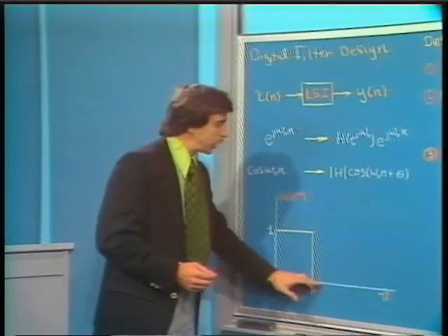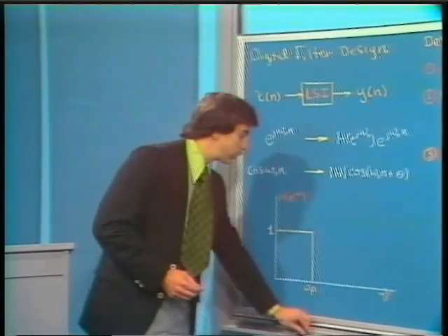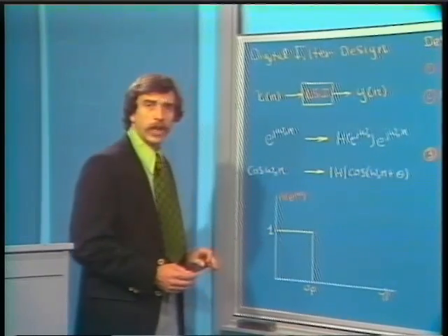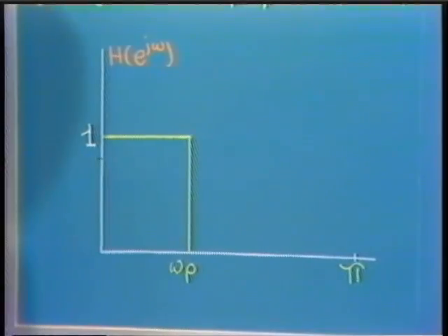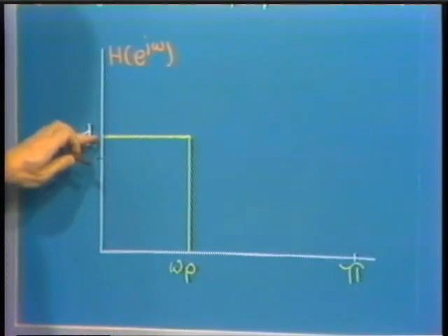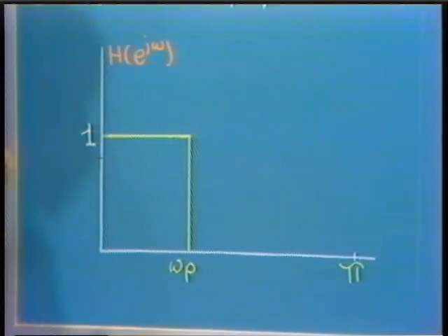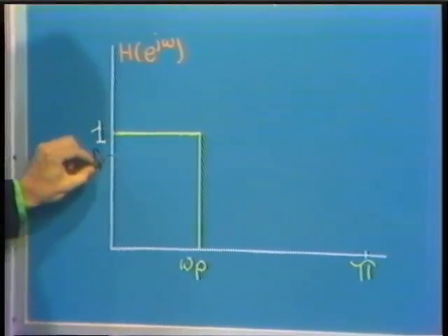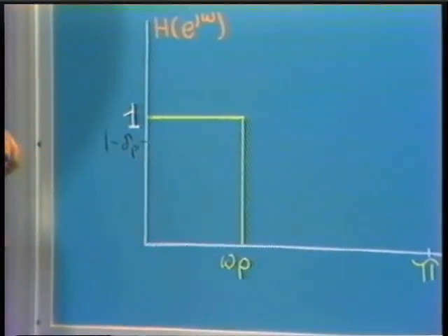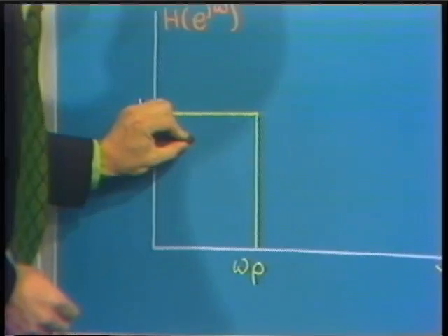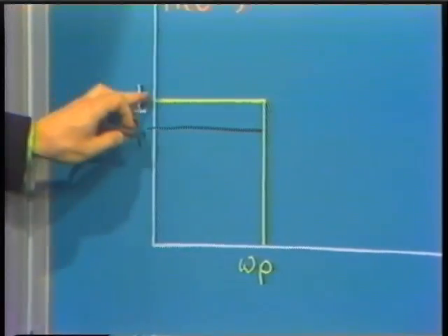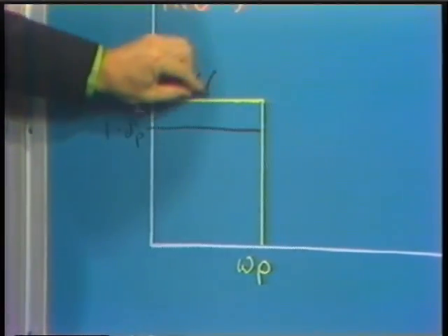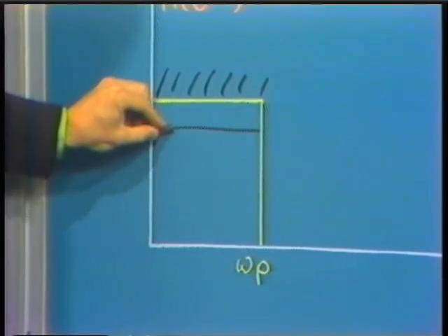So whereas we talk ideally about a filter characteristic, as I've indicated here, in fact, we have to allow some deviation from this ideal characteristic so that we would permit, as an example, a frequency response, rather than being unity in the passband, to deviate from unity by some amount, and let's designate that by, say, delta sub p, denoting a passband deviation, so that in fact what we might specify is a filter which in the passband, in the band of frequencies that we wish to pass, rather than being exactly unity, is constrained in the interval between unity and 1 minus delta sub p.